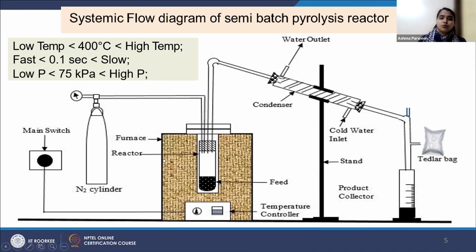So here is a diagram showing pyrolysis. In the center is the pyrolysis reactor. It is kept inside a furnace to provide the temperature. In pyrolysis, by temperature, we decompose the waste. Also, we need a carrier gas to carry the volatiles and gas produced in the pyrolysis reactor outside of the reactor, where they are collected. So in pyrolysis, we get all three components. A condenser is provided in which the gas is condensed to get the bio oil. We get the bio char, or solid, as an end product, and also we get gas.